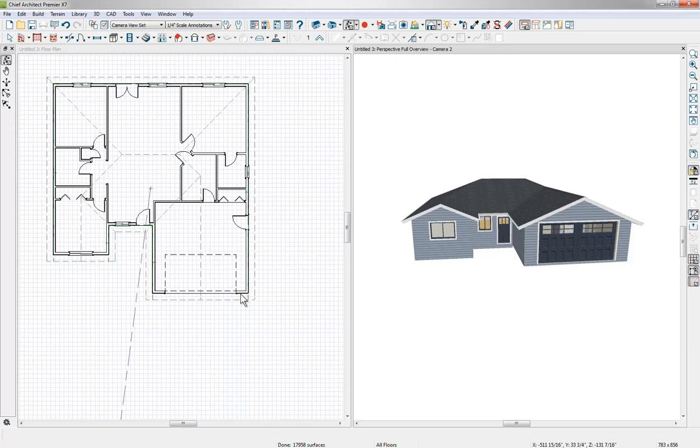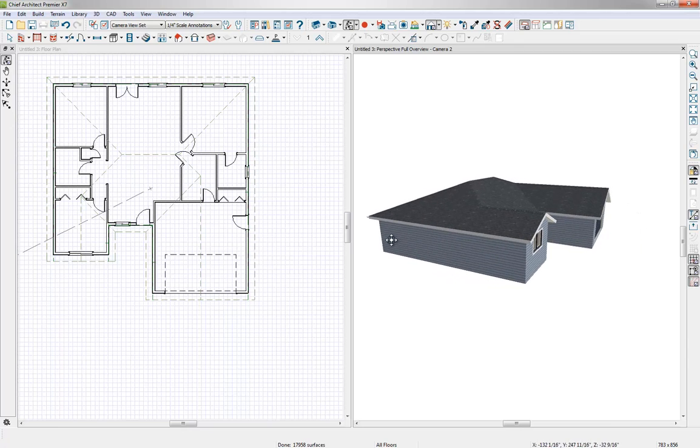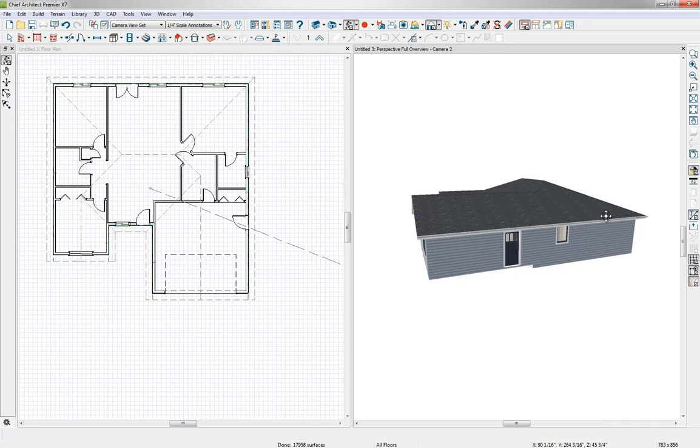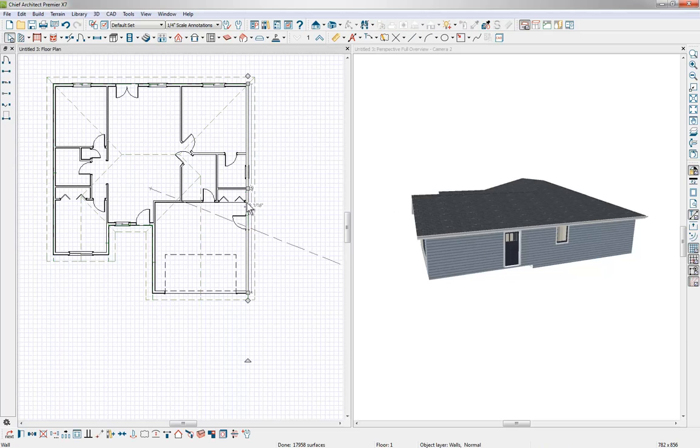We can also group select. If you have multiple gables, we can group select that. Now on the side of the house, we have a gable that runs across here, and we'll want to also have a gable run across on this side that comes up. So we'll need to split this long wall in half. Right now this is shown as one long wall, so we'll want to split that in half so we can tell the software where those gables run to on either side.